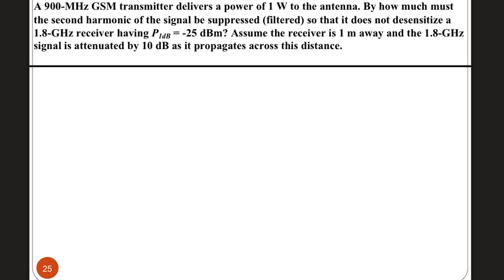Try to solve it backward. Start from what you want to receive from that second harmonic and then reverse the effect of the drop in the channel. This will give you how much you need to transmit in the second harmonic. Right? Solve it backward, from the end back.